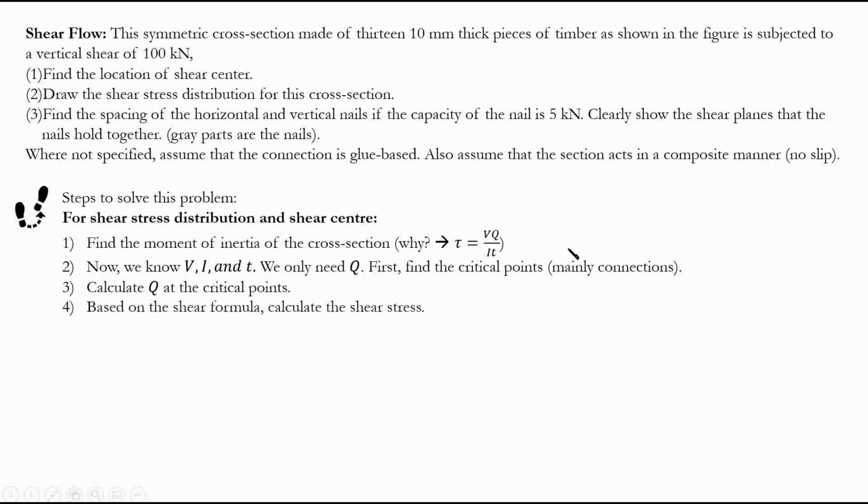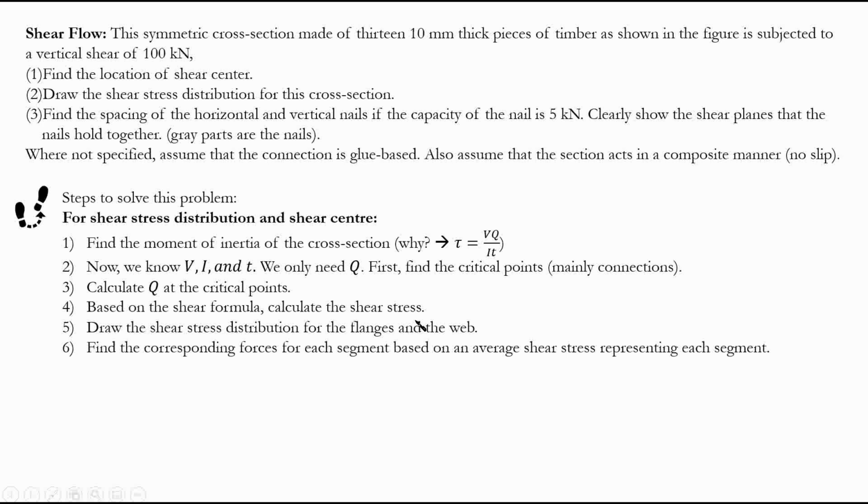And again, based on the shear formula, calculate the shear stress. How? Of course, we know V, I, T, and now we calculate the Q. So we have everything to calculate this tau value. And it says draw the shear stress distribution for the flanges and web. And of course, when we have the shear stress, we can do everything else and find the corresponding force for each segment. And we're going to talk about these as well.